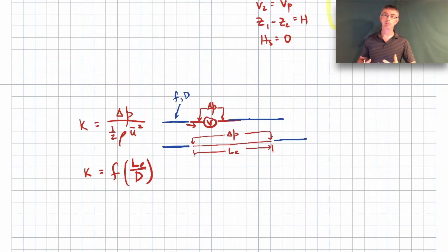So sometimes you'll see minor loss coefficients given in terms of equivalent lengths of pipe. And the way to find the K value for that is you just take the friction factor of the pipe leading into it, same with the diameter, and then use that equivalent length in this manner so that the loss coefficient using the equivalent length of pipe would be the same as the loss coefficient you would get if you actually had the real device there. So that's called an equivalent length of pipe. Again, it's kind of an older way of expressing losses.